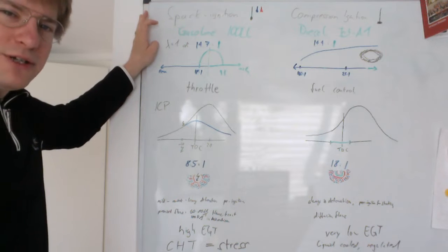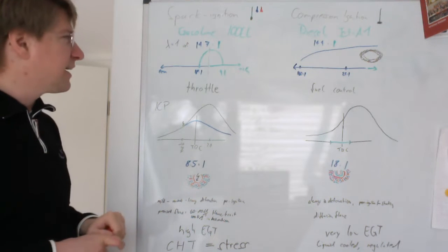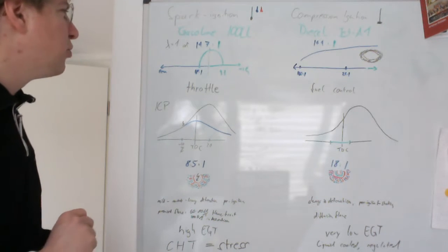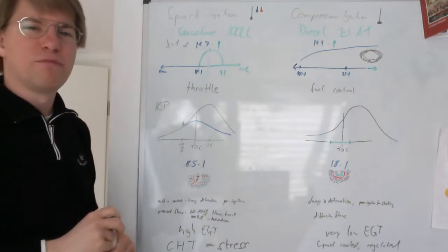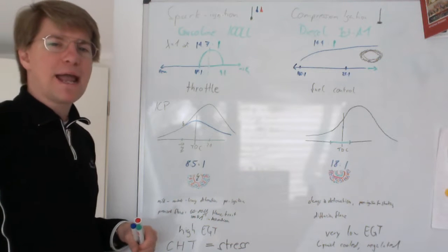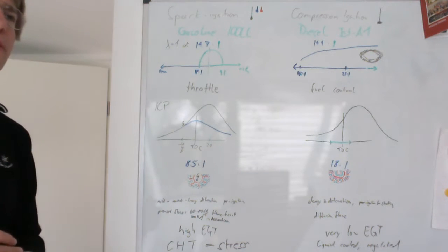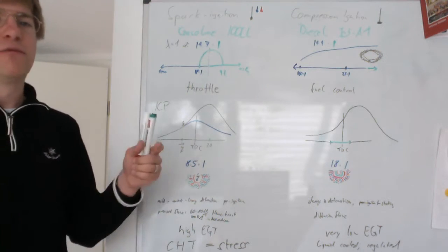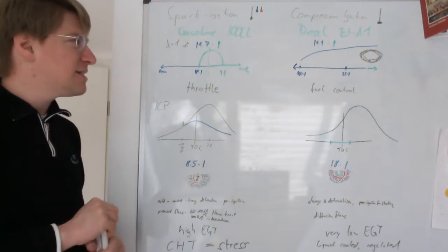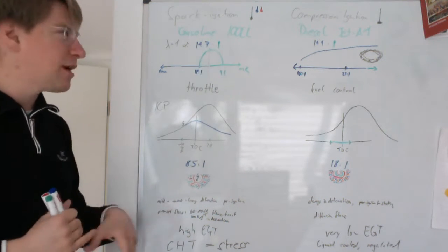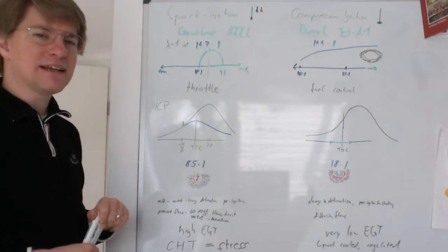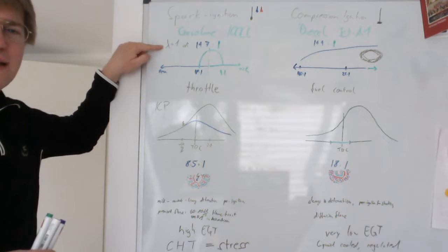All right, so in order to burn our fuel, the gasoline, we need a certain mixture. We need air, or more precisely oxygen, and the fuel. And the optimum ratio of burning air and fuel in a gasoline-powered engine is 14.7 to 1 by weight. So we need 14.7 kilograms of air, which is a certain volume, because when you multiply it by rho, air has a density, it's not weightless. So 14.7 kilograms of air and 1 kilogram of fuel. That mixture is what we call lambda equals 1.